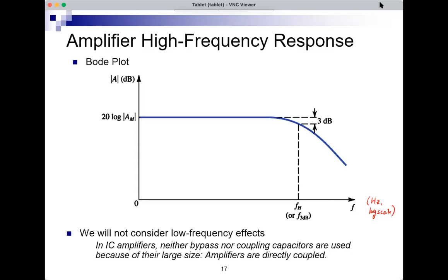And if you look at the blue curve, this is how the gain would vary with frequency. So there is a range for which the gain is almost constant at low frequency for all this range here. You see that the gain is almost constant. This extends all the way to this point here. And for these small frequencies, the gain is constant at AM. AM we call the low frequency gain. And in dB, the gain is 20 log AM. So nothing really happens there. And we just need to know what this AM is, and we know how to do that.